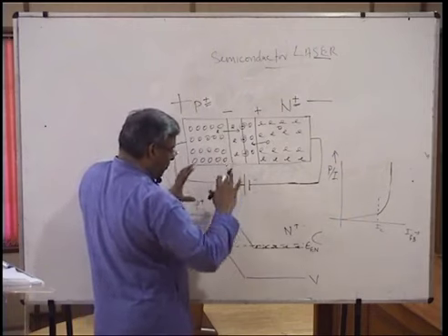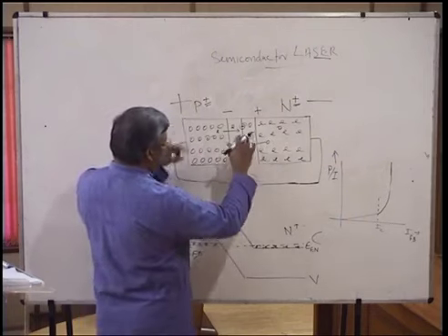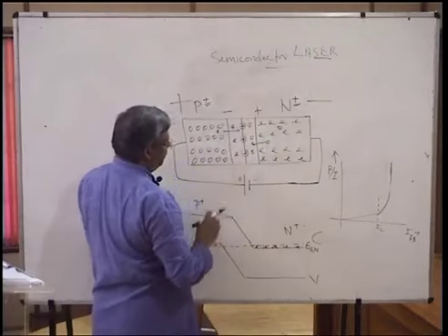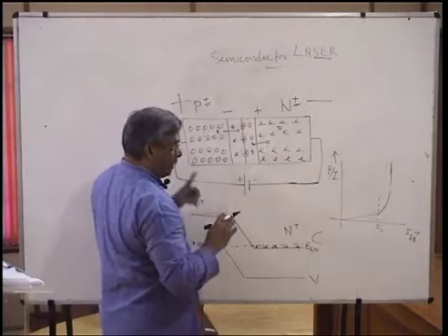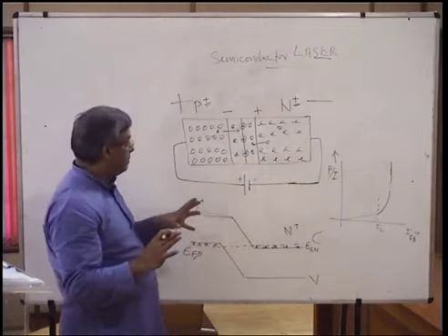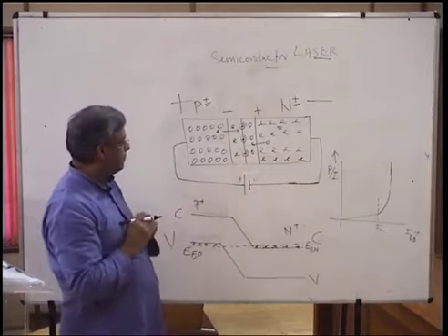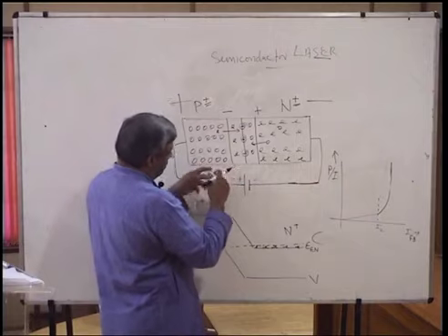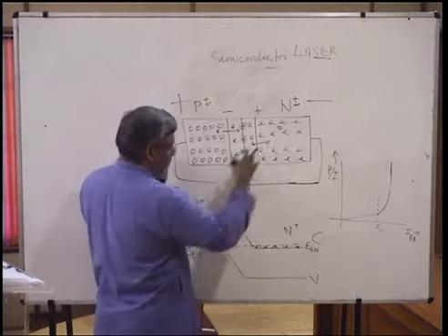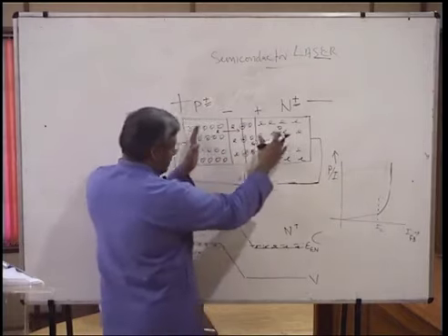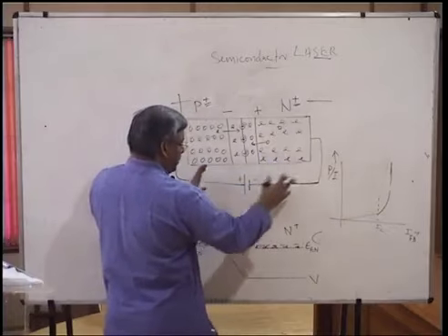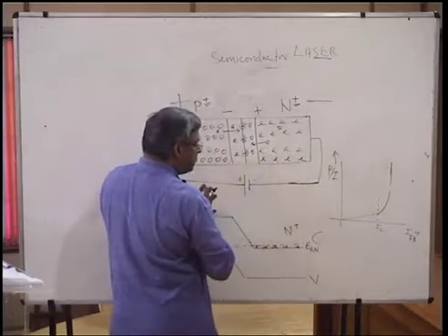Such an amount of doping should be there for this material to operate as a laser. And I hope you know the difference between an LED and a laser. An LED produces light when a PN junction is forward biased. It is just a PN junction, not a P plus N plus junction. A forward biased PN junction gives you an LED.